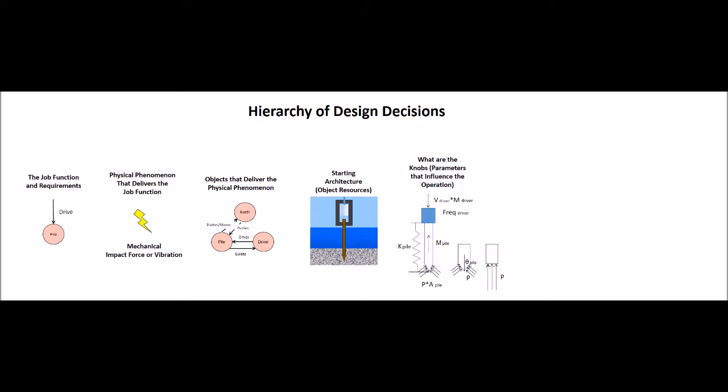This pressure times the cross-sectional area of the pile is a resisting force that slows the pile as it drives into the ground. The pressure at the tip is controlled by the sharpness or tip angle of the pile. Moving the soil sidewards rather than downwards requires less pressure, especially closer to the surface. That is why a sharp tip angle makes the driving faster. The force pushing back from the ground is greatly reduced.